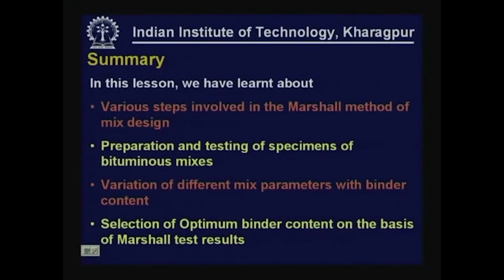To summarize, in this lesson we learnt about various steps involved in the Marshall method of mix design. We also discussed the preparation and testing of specimens of bituminous mixes. We also discussed how various mix parameters vary with binder content, and how to select optimum binder content on the basis of Marshall test results.